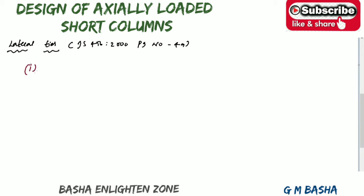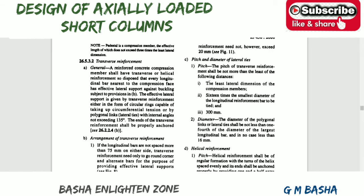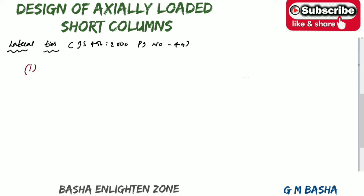Then our first point, observe in the code book: the pitch of the transverse reinforcement shall be not more than the least of the following, and the diameter of the lateral ties. It talks about the diameter of the lateral ties and it talks about the pitch. So what is the meaning of the pitch here? Means, for example, in the beams we used to provide spacing. In the beams we used to provide stirrups.